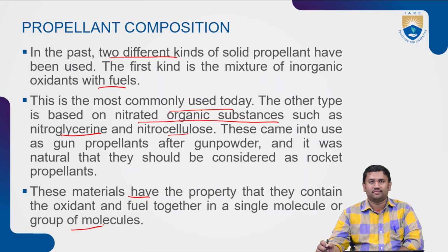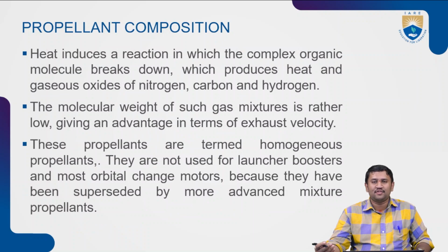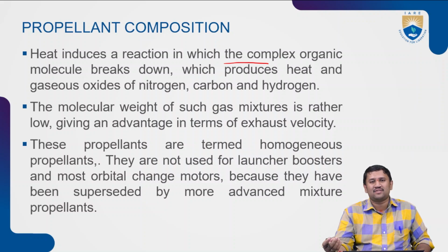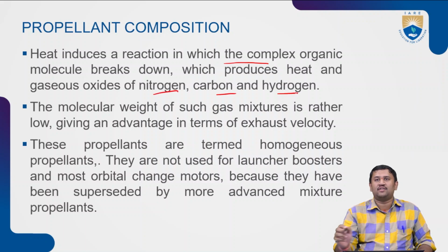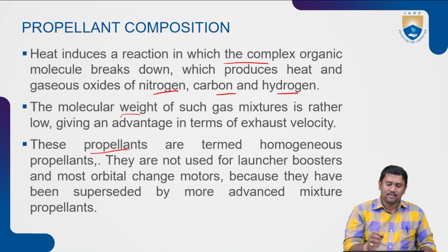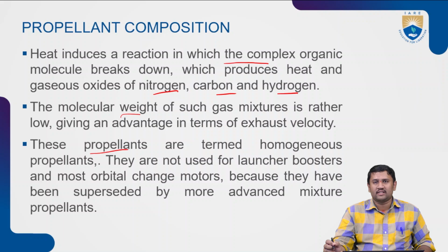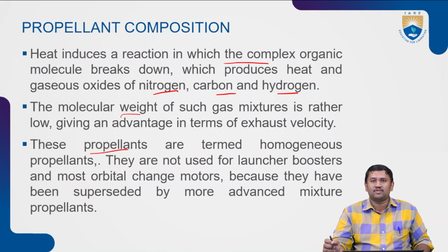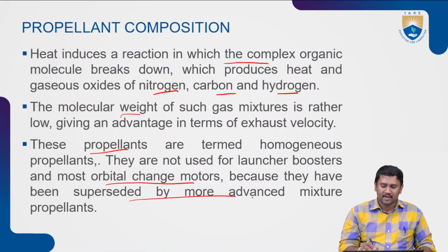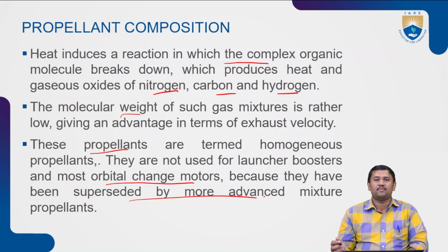These materials have the property that they contain the oxidant and the fuel together in a single molecule or a group of molecules. The heat induces a reaction in which the complex organic molecules break down to produce heat as well as the gaseous oxides of nitrogen, carbon as well as hydrogen. The molecular weight of such a gas mixture is rather low, giving an advantage in terms of exhaust velocity. These propellants are termed homogeneous propellants. They are not used for launcher boosters but in most orbital change motors. They have been superseded by more advanced mixtures of propellants that we will be discussing further.